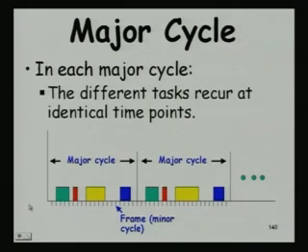To start, at time 0, a periodic timer is set, let us say for 15 milliseconds, or 15 milliseconds is too much, maybe let us say some 50 microseconds or something, depending on the application. And then it keeps on giving these interrupts every 50 microseconds. Is that okay? Yeah, the smaller ones are the frames which are obtained through interrupts from a periodic timer.